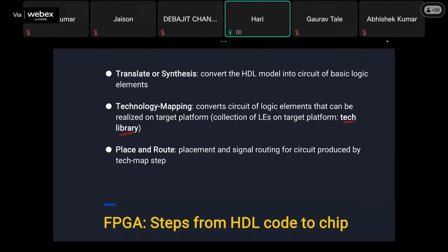That's what I'm speaking about: where exactly should it be placed on the FPGA? The FPGA itself has a lot of configurable logic blocks. It can be some 10,000. It starts from some thousand and extends to some lakhs. Based on the cost of the FPGA, you will get a lot of configurable logic blocks to program. So these are the steps. And then at the end, you can use the bitstream. In comparison with a microcontroller, you can consider machine code, right? Machine code is nothing but your program. And here bitstreams are nothing but your configuration elements to run your program.